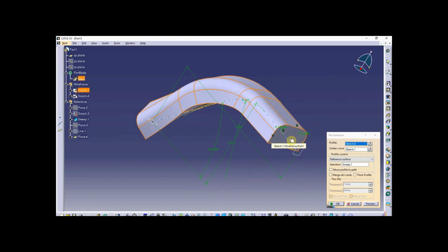completely intersecting the current body or solid geometry in the current body, then you can turn on merged ends and it will extrapolate out and merge in with solid geometry in the current body. Much easier probably to demo, and I'll throw that into another demo later. But the merged ends allows you to extrapolate the ends of the sweep into solid geometry in the current body.